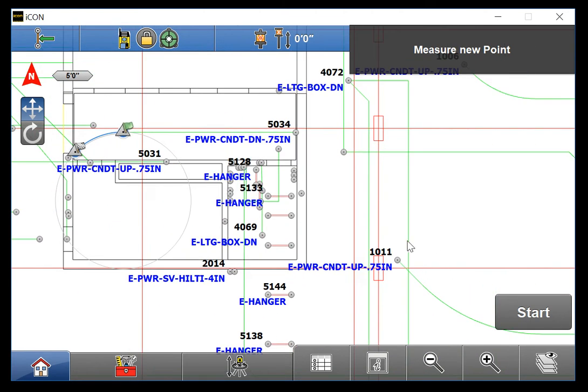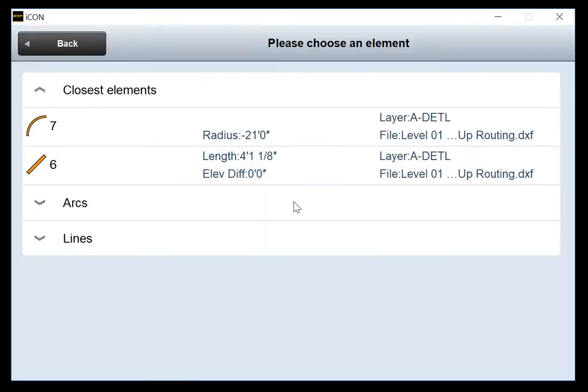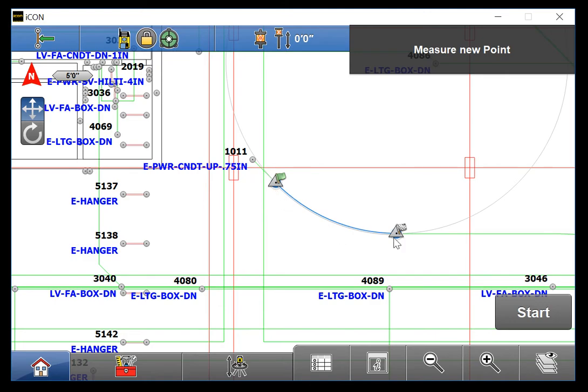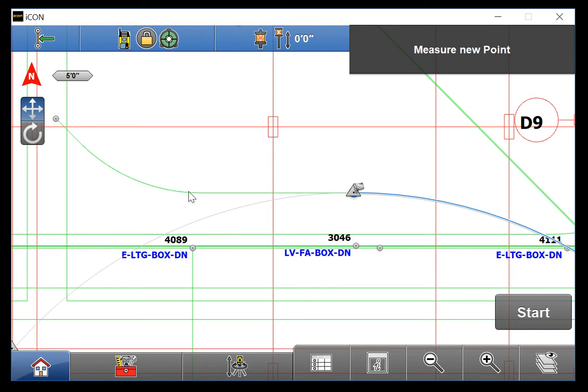The reason it's important to recognize that you can use background lines, say for underground excavating, utility conduits, you could lay out the underground utility lines, and notice that the lines don't need to have points associated with them in order for you to lay them out. For now, let's use a straight line for the purposes of the information I'm going to show you.